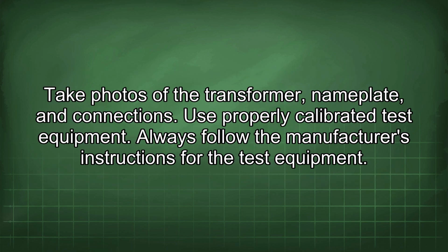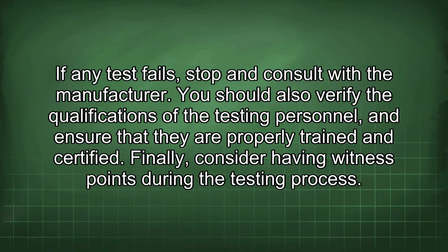Take photos of the transformer, nameplate, and connections. Use properly calibrated test equipment. Always follow the manufacturer's instructions for the test equipment. If any test fails, stop and consult with the manufacturer. You should also verify the qualifications of the testing personnel and ensure that they are properly trained and certified.